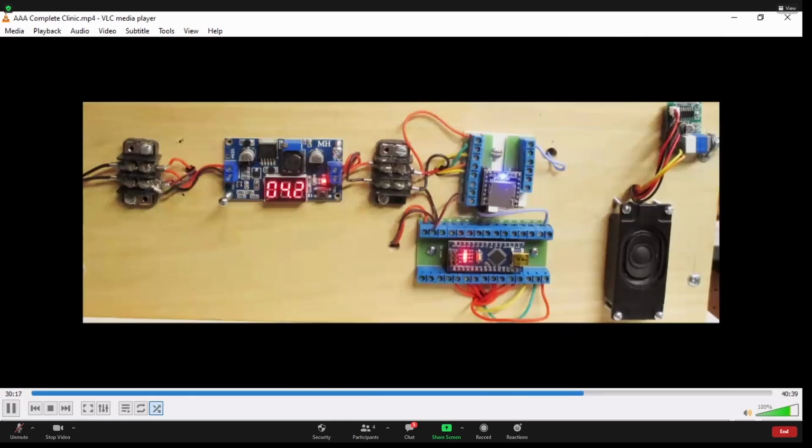I could run it from the 5-volt pin of the Arduino, but I was afraid too much power would be consumed, so downstream of the power supply's barrier strip, I wired in a buck converter, or voltage regulator I purchased from Amazon. Downstream of the buck converter, I wired in another barrier strip. But before I wired in the MP3 player and the amplifier, I dialed down the converter to 4.2 volts because the web said it ran better at this lower voltage.